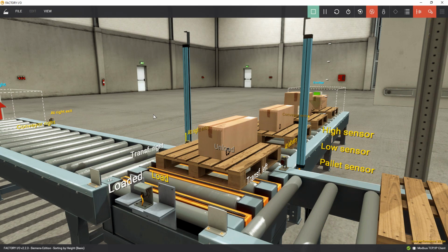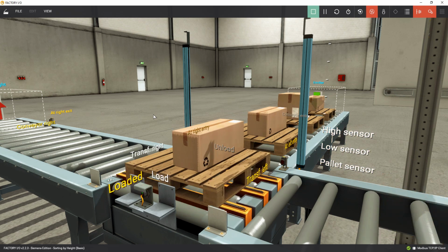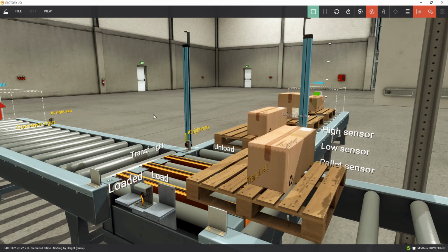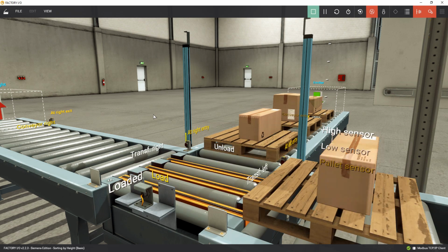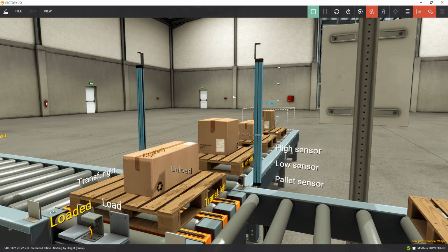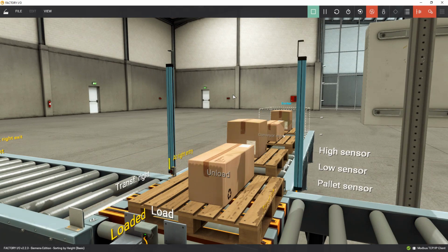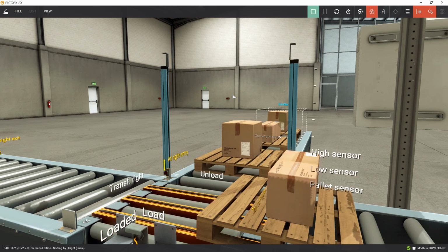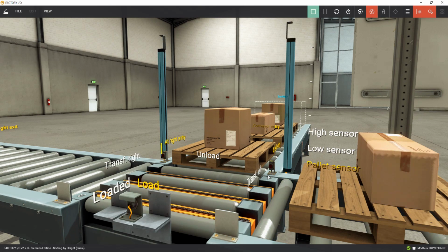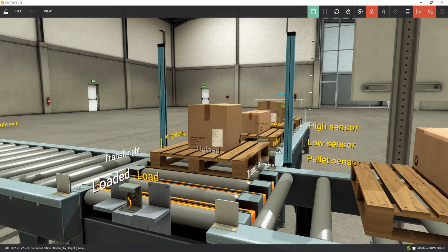Alright, it looks like some boxes are longer than the 8 seconds. It is best to use 10 seconds. When you look at the point where they stop running, you can tell that the 8 seconds that is supposed to stop the conveyor belt is not enough. Look, it stops it while it's still going. So it's easy for a box not to pass through. So the 8 seconds there is small, and it's doing only big boxes.